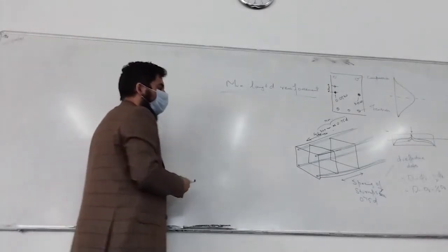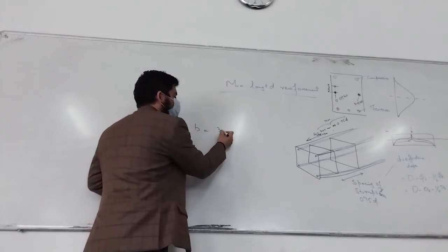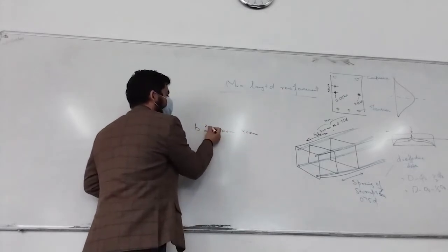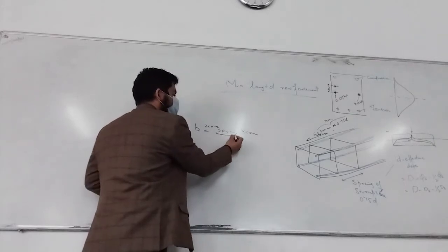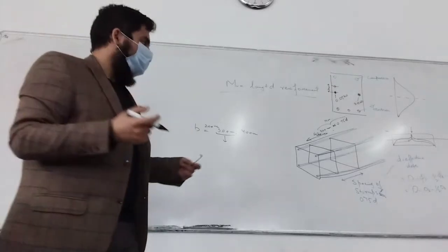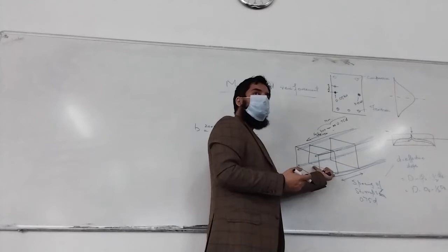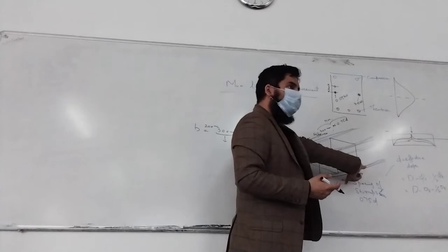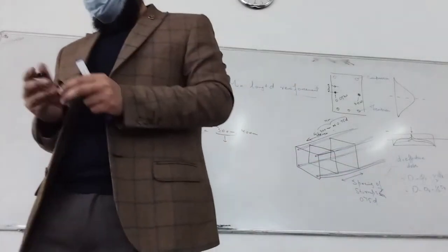What is the width of a beam? 300 mm till 400 mm, minimum 200 mm, maximum around 400 mm. What is the center position? 300 mm. So the width, you take it as around an average of 300 mm. You replicate that and keep the maximum spacing between the two stirrups as 300 mm.